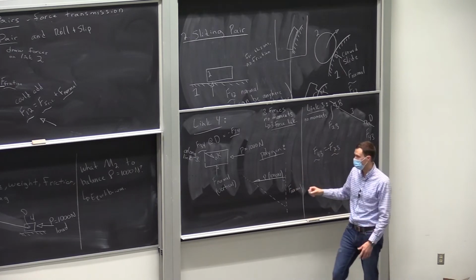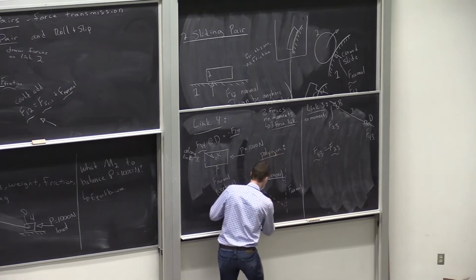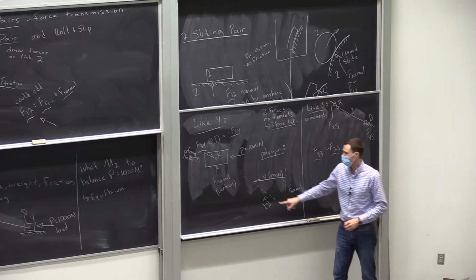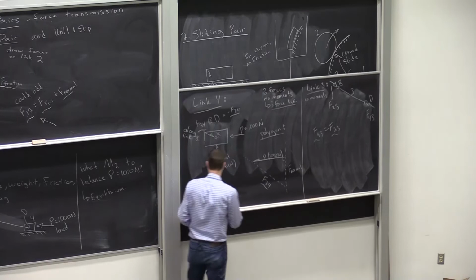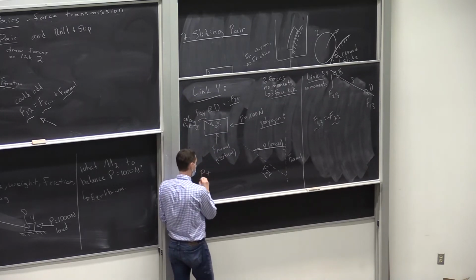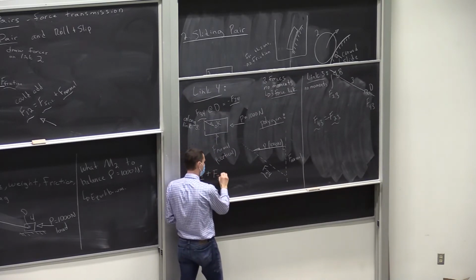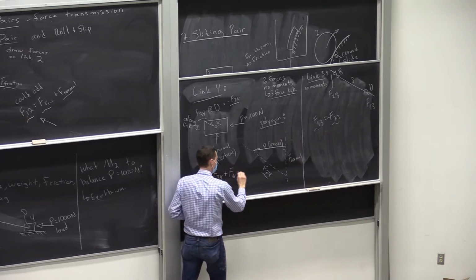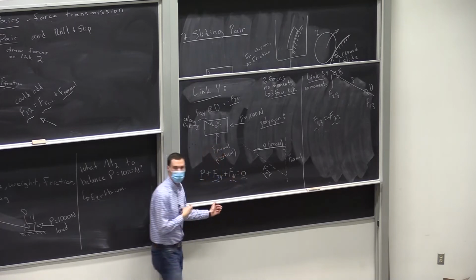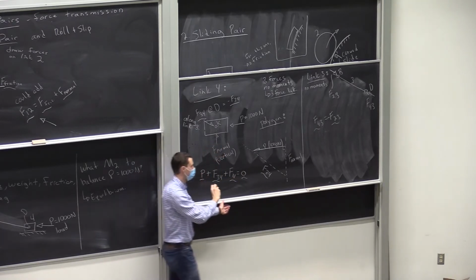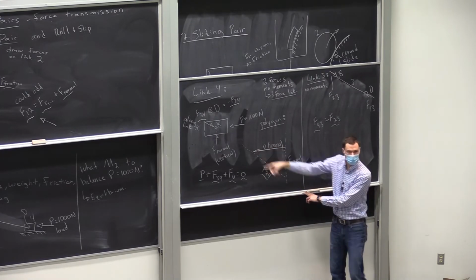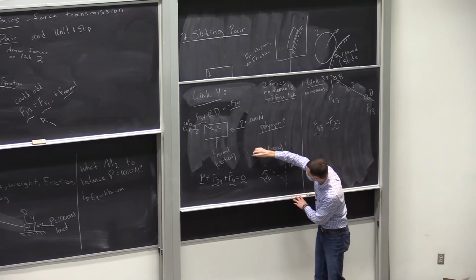Great, and this is enough. We've solved the polygon here. And you'll recall from last time, these need to add. Our polygon is an addition: P plus F3/4 plus the normal force equals 0. Plus, plus, plus. That's what we always have for force polygons. So it needs to go around the loop. P started off to the left, so that's like a counterclockwise loop here.